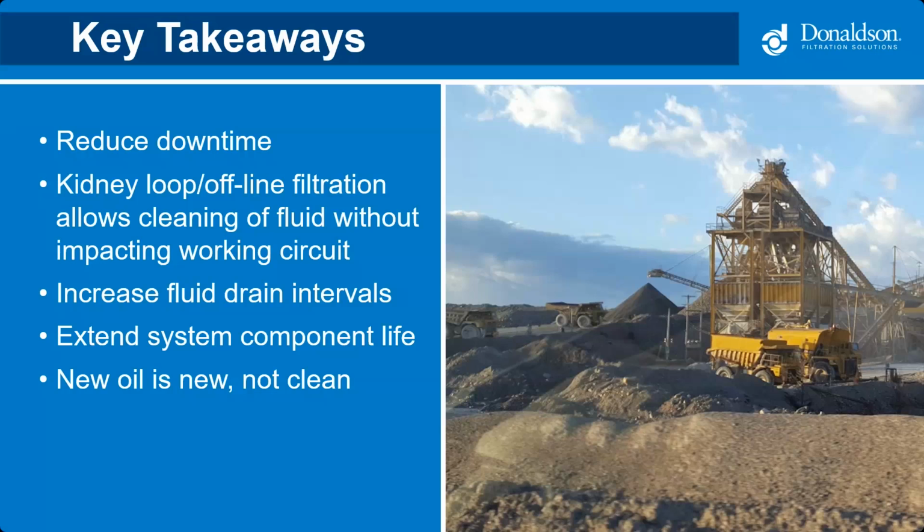We can increase fluid drain intervals. We can extend system component life. And last, but definitely not least, always remember that new oil is new, but it's not necessarily clean. So we can use filter carts to transfer that fluid into those circuits without causing any damage to them by adding particulates to that circuit.